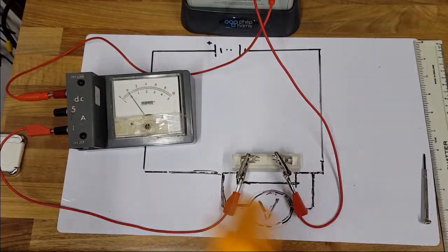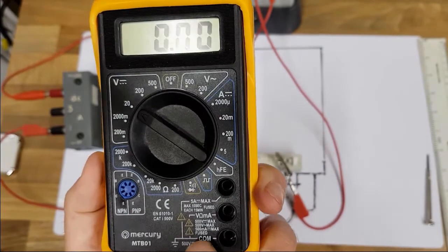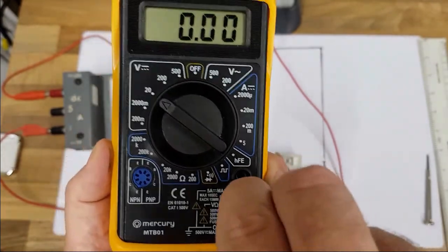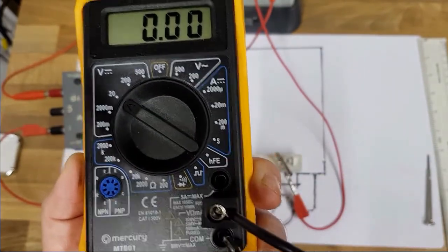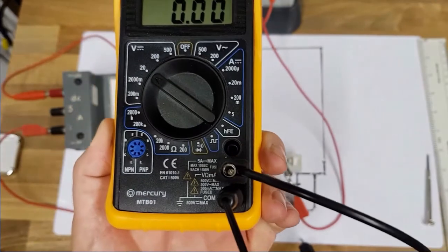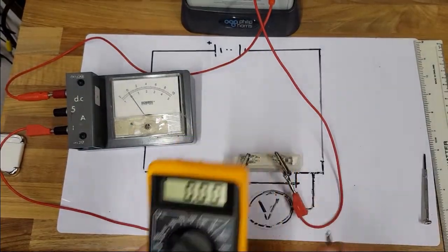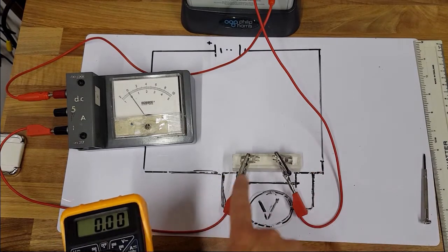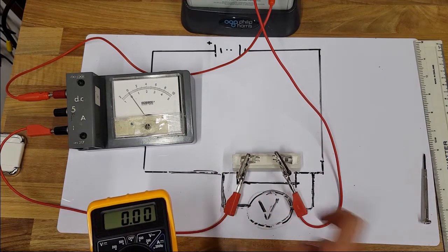Okay, I'm going to plug in a wire at the top here at the volts, ohms and milliamps. We're not using very high current, so we can use that one, and we use the COM hole at the bottom. Then, if you take a look here, the connections go either side of the resistor, so that's exactly what I'm going to do. I'm going to plug it into either side of the resistor on these two cables.